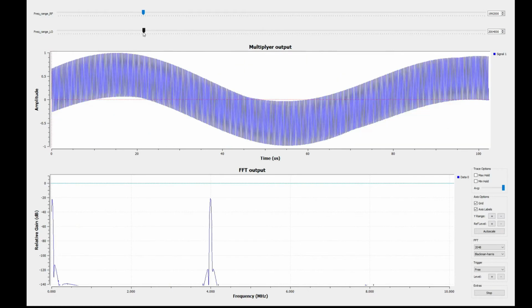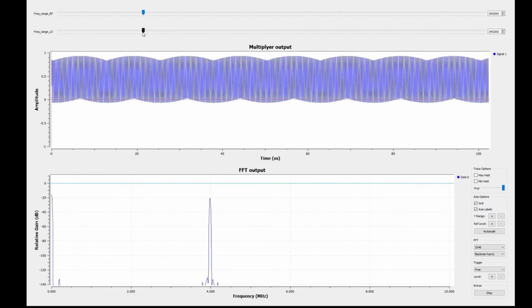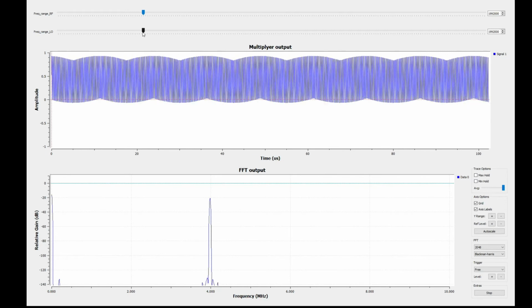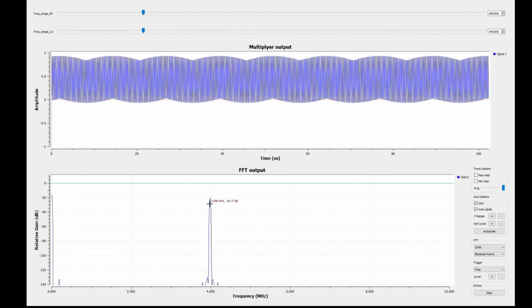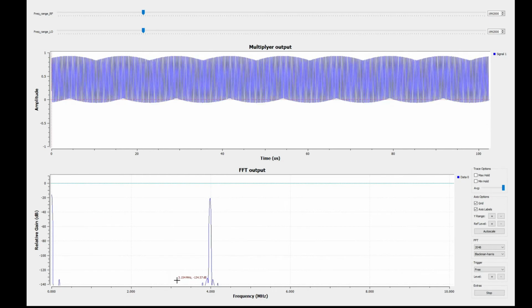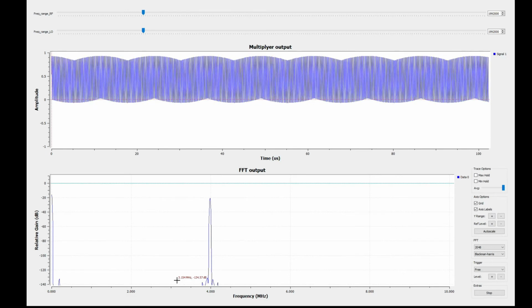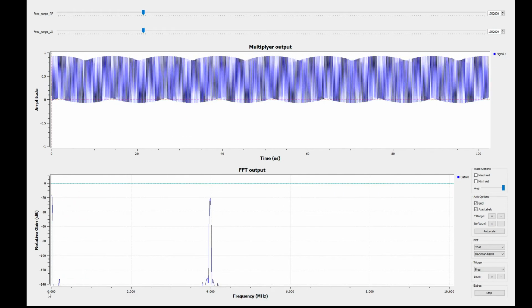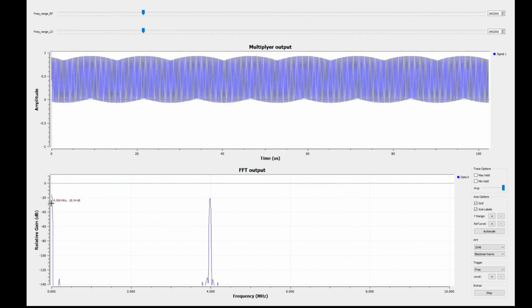What happens if both frequencies are exactly the same? In this case we have 2 megahertz and 2 megahertz. What we get is 0, plus or minus 0, and 4 megahertz. And SDRs are also called zero frequency mixers, because you mix the signal down into the audio frequency range, and you can detect and demodulate directly in the audio range.